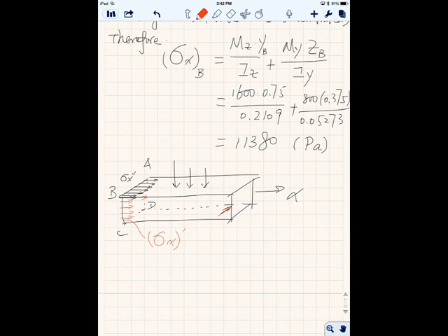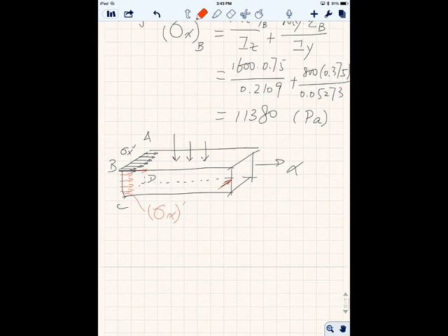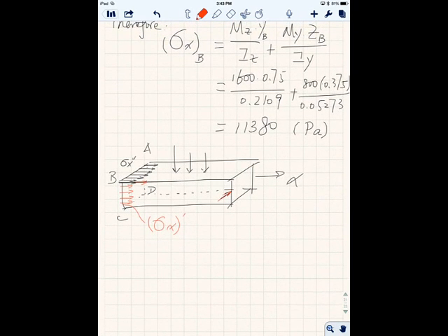And then yb and zb, of course, are always positive numbers because that's a distance, right? And Iz and Iy are positive numbers. So I think in the textbook, it has a negative number over here because of the definition of the bending moment. But I don't really like it because it's getting confusing. Because by looking at these figures, both black and red are pointing in the same direction, so of course I can just add them, right? So I think this is easy, and that's why I didn't really follow the textbook over here. I think that might be easy to understand.